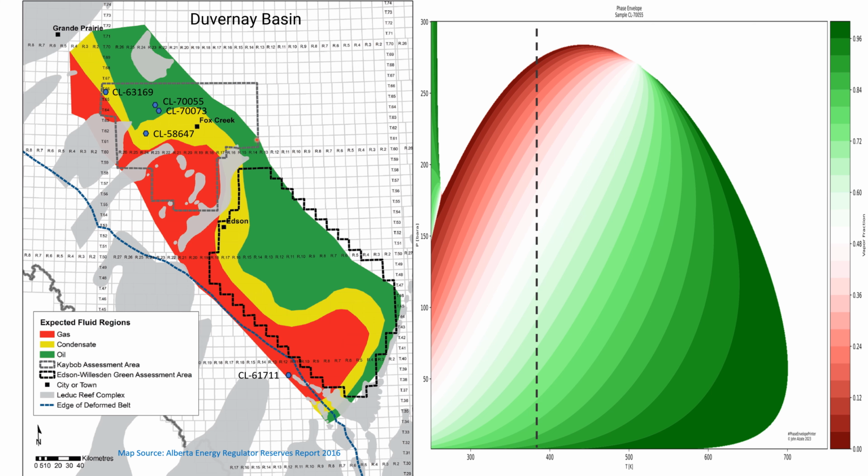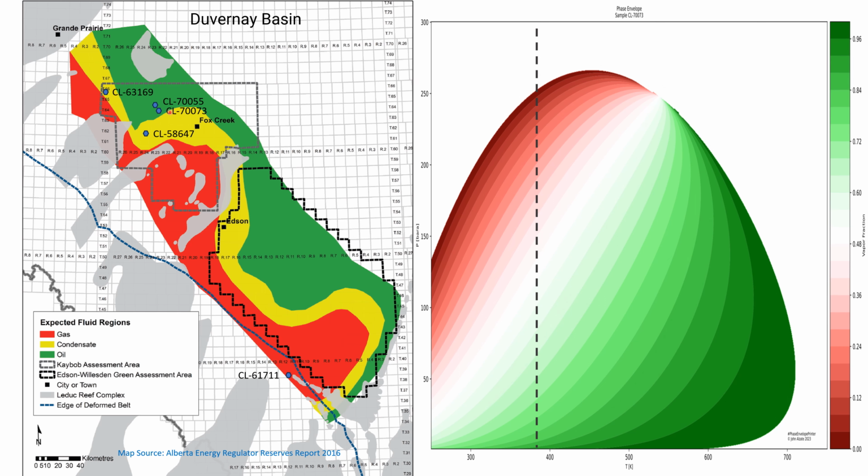And my fifth fluid, my last fluid, is a heavier oil. It has a lower bubble point pressure as compared with the previous fluid. The condensate term is also higher as compared to all the four previous fluids, and in the same region of interest, 250 to 750 Kelvin and 0 to 300 bar, this fluid does not exceed that unstable tail, right? Maybe if we explore lower temperature, maybe, but at the moment I don't know.